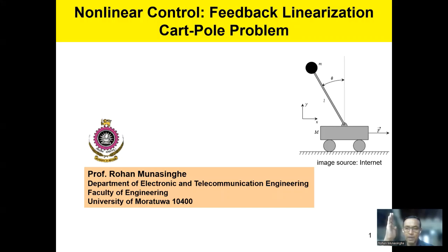But if it moves more than that, some 30, 40 degrees, sometimes going downwards, of course, your linear quadratic regulators, your linear controllers are helpless, they cannot stabilize the plant. So in that case, you really need some sort of nonlinear controls. This is the first time we are going to look at how we can design and build a nonlinear controller. That is the topic today.